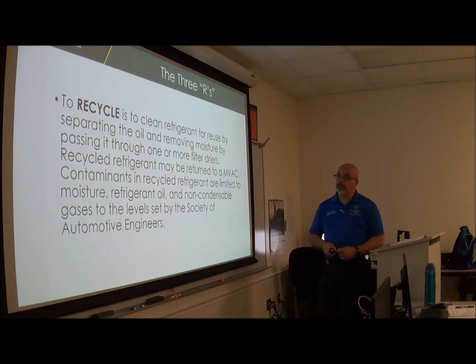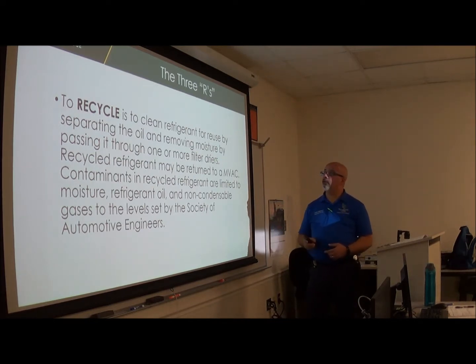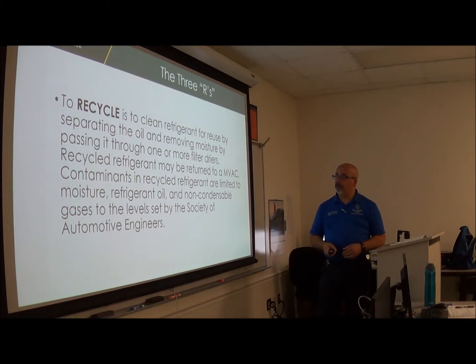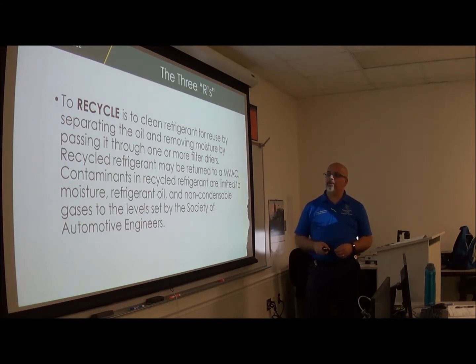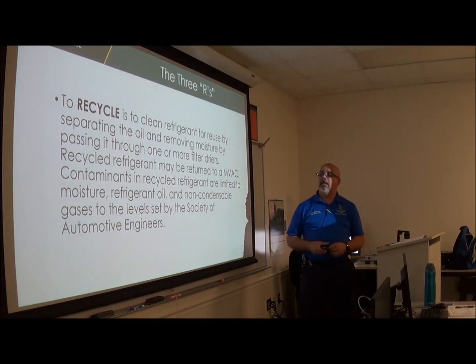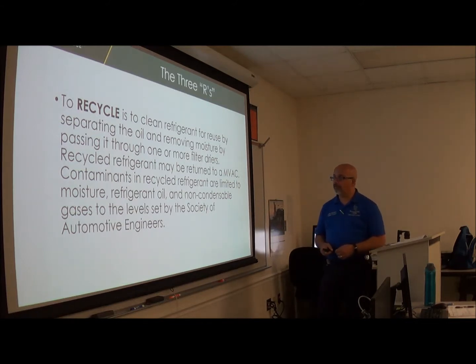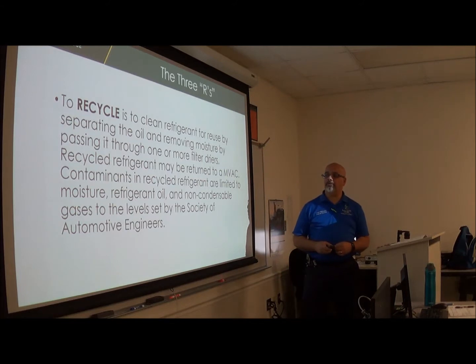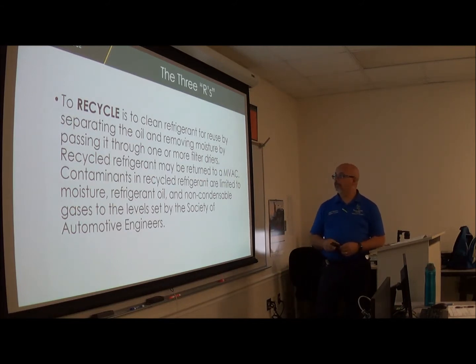To recycle is to clean refrigerant for reuse by separating the oil and removing moisture by passing it through one or more filter dryers. Recycled refrigerant may be returned to a MVAC. Contaminants in recycled refrigerant are limited to moisture, refrigerant oil, and non-condensable gases to the levels set by the Society of Automotive Engineers.